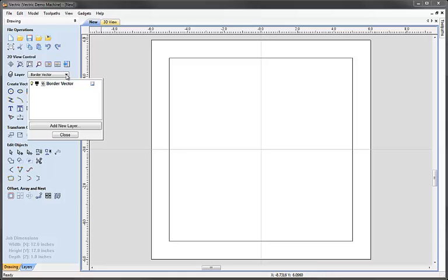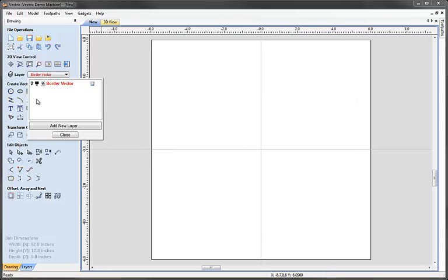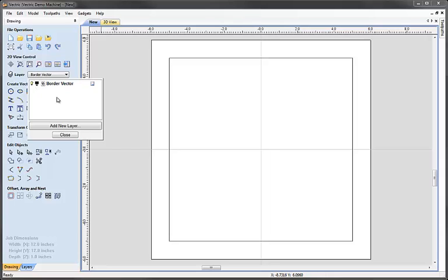Now it's possible for me to undraw this layer so that the item on it is not displayed. If I click on the light bulb here in the list, then it undraws it. You'll also notice that the text turns red. What that's indicating to me is that this is the active layer, but that I have it currently undrawn. Generally speaking, you're going to want your active layer to be visible in almost all situations. So the red text is a bit of a warning to say at this point you may want to switch that layer back on, or you might want to choose another layer in the list if you have one.